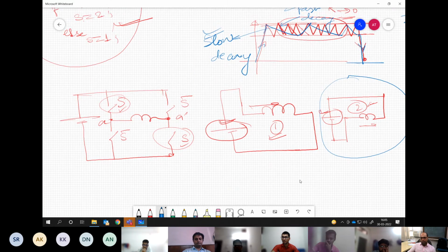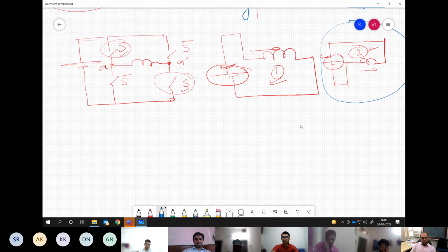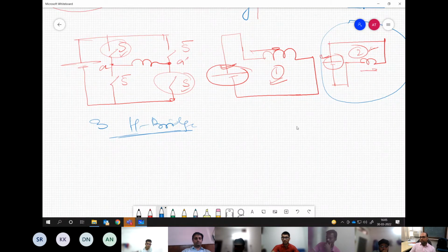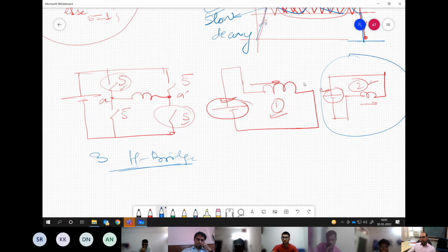So if you have a 3-phase motor to operate an SRM, you will have 3 full bridge converters, 3 H bridges. Or sometimes you may connect only 3 half bridges and all the second terminals connected to the negative DC, but there we will lose the capability of fast decay.